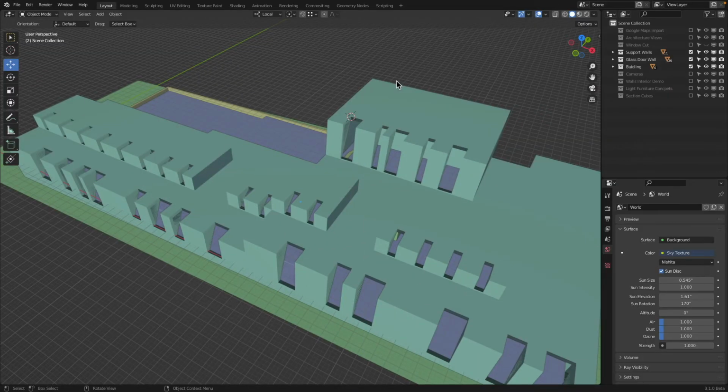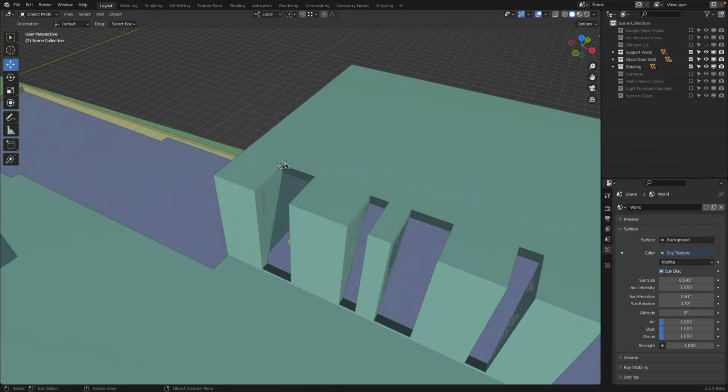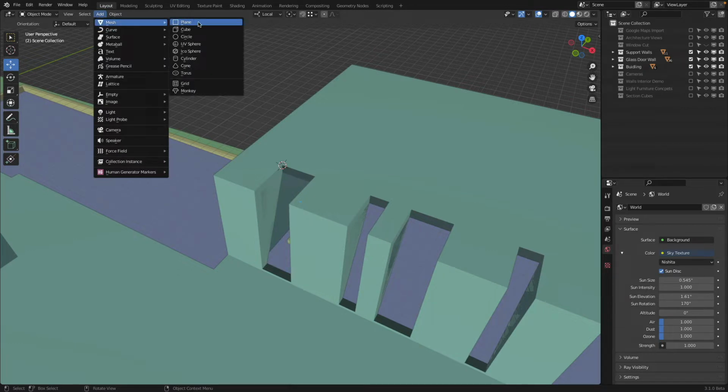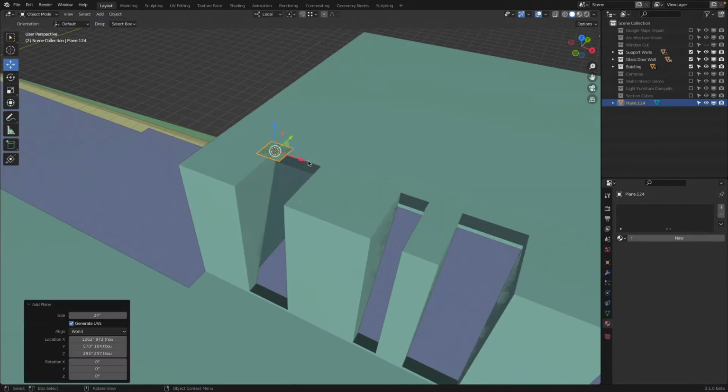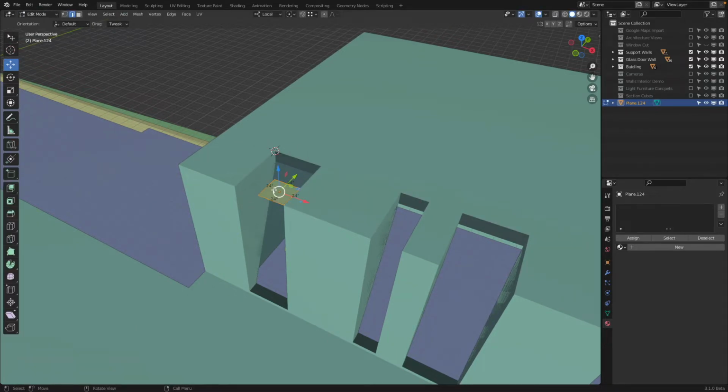So let's create the geometry for all these window openings. I have the 3D cursor positioned. Point snapping, move command is on. Add new mesh plane. Then I can move, hold Control and snap. Hold, snap. Going to edit mode, edge select, bring this over, hold Control.